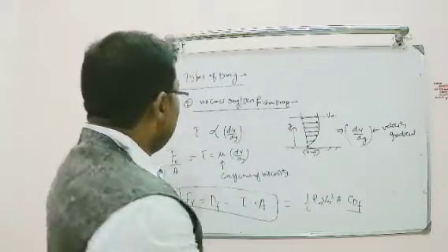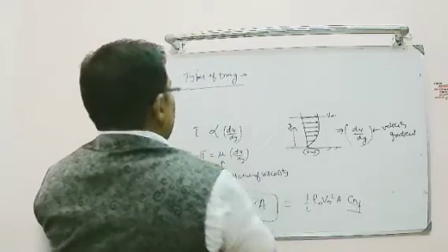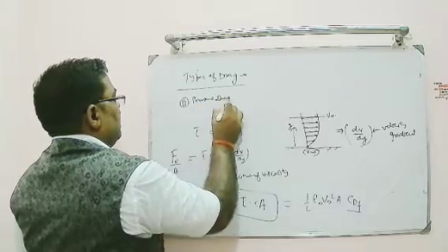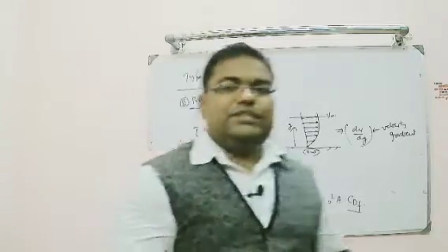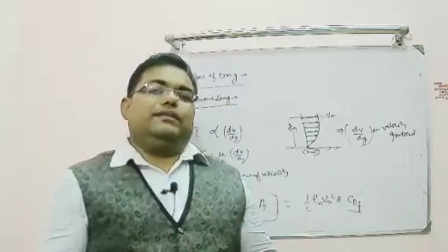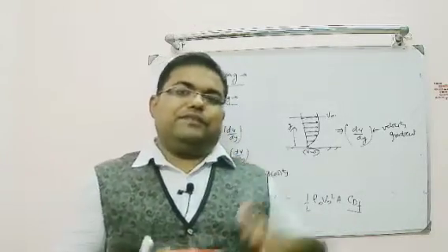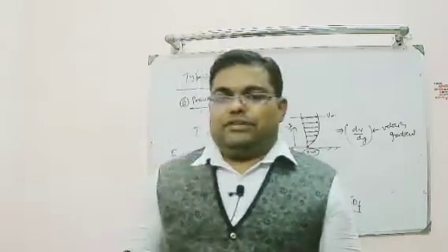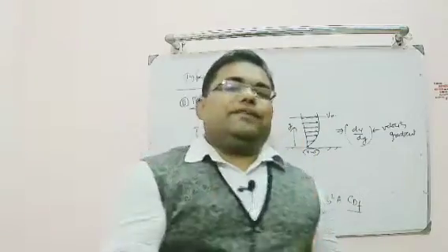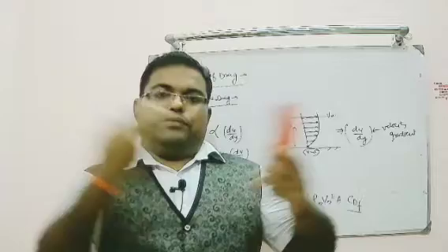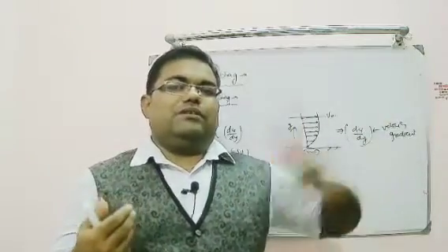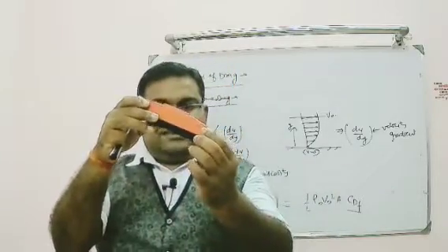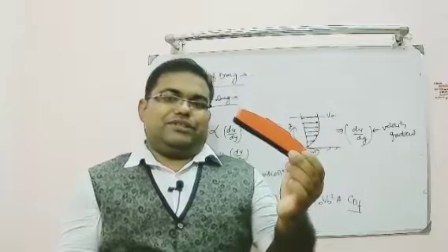Now, skin friction drag is over. Next one is pressure drag. So pressure drag occurs due to the shape of an object. If the object is moving, pressure drag occurs due to the pressure difference between the front facing flow and the rear flow. If you take the difference between these two, that will give the pressure drag. So as I said, if my plate is moving like this, it will have more pressure drag because on this side pressure will be more, and all of a sudden pressure will be less. Also it will resist the motion of the object. So pressure drag will be more in this case. If I am keeping it like this, in this case pressure drag will be less because there is less obstruction to the flow.